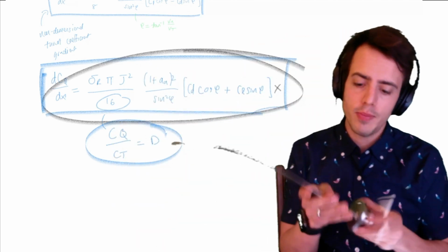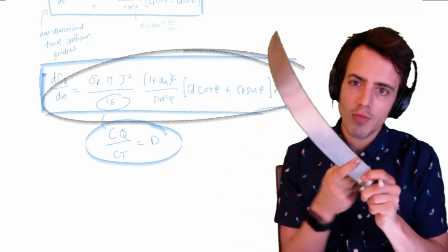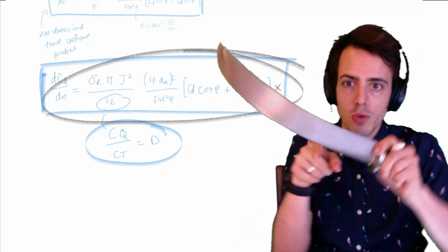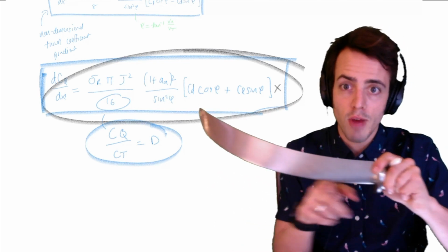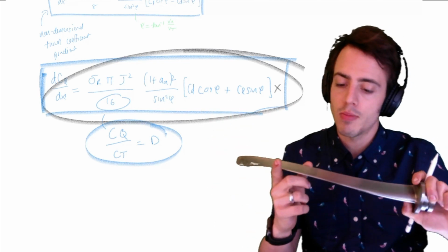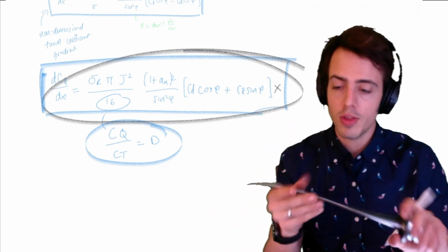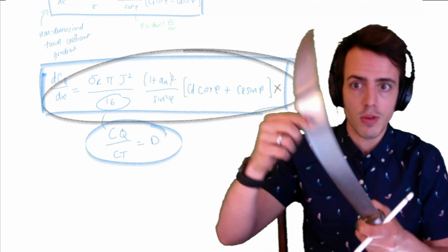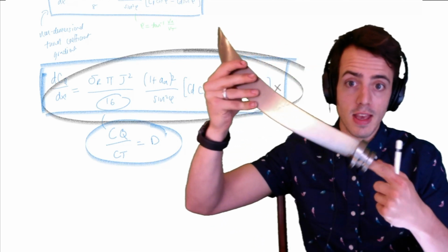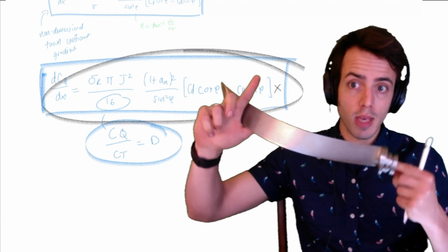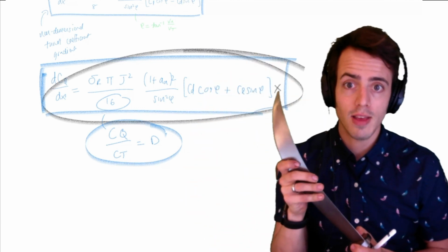what the propeller's doing, the propeller's spinning round, and if it's producing thrust, the thrust is just the force that is pulling forwards. It doesn't change with radial position. It doesn't produce more thrust just because I'm further outboard. By contrast, the torque is largely due to the drag on the blade, so pushing back this way, and it's experienced at the hub. So there is a moment arm that we care about. So that moment arm gives rise to this x here.